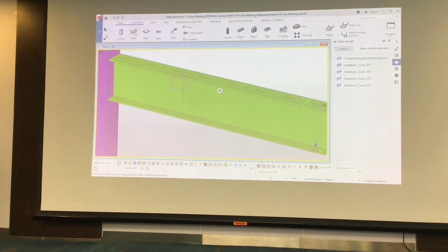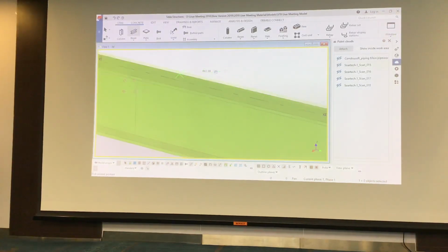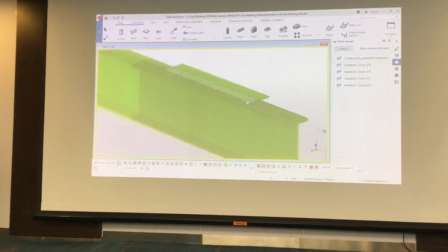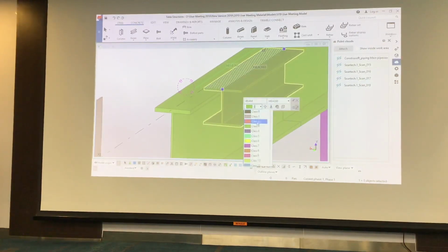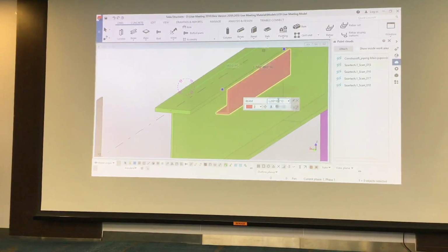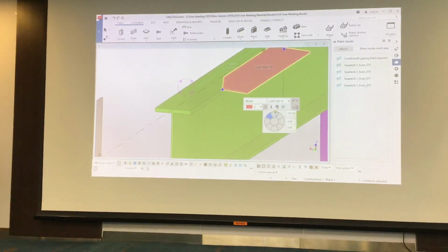So let me just repeat some stuff. So if I go, let's say I'm going to draw a beam in here. The beam goes from, let's say, the nearest point of here, and it goes to the nearest point of here, like so. So I've got a quick beam in there, like that. I'll click on this, I'll use the mini toolbar, I'll say make that different colour. And let's say, let's make this L200 by 100 by 10. By 10. So click that, make the size. Then click on here, position that as it needs to be positioned, or rotate it to the correct rotation.